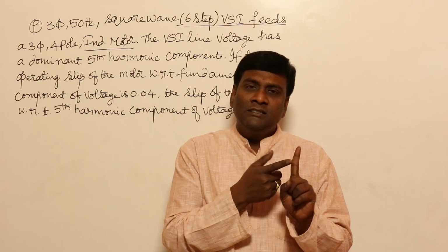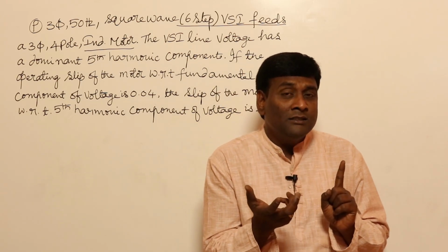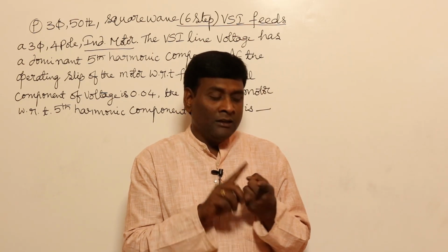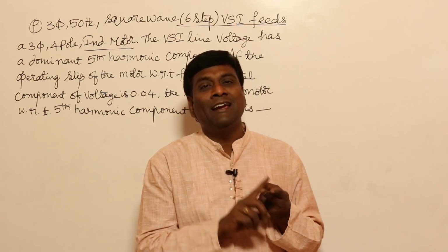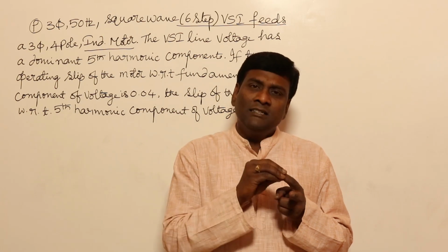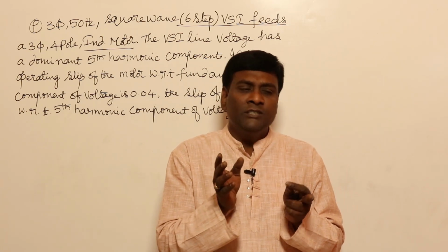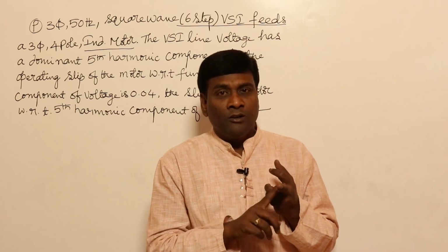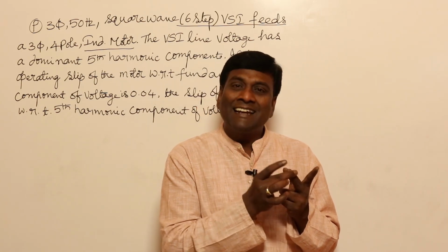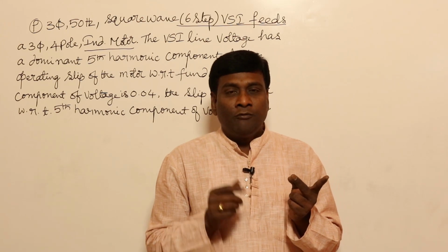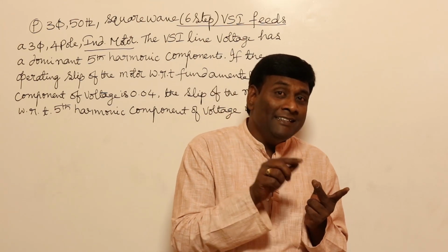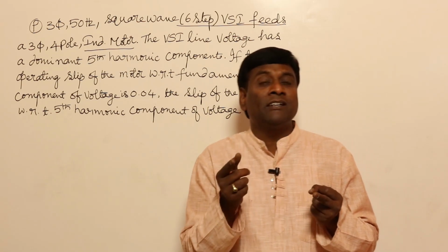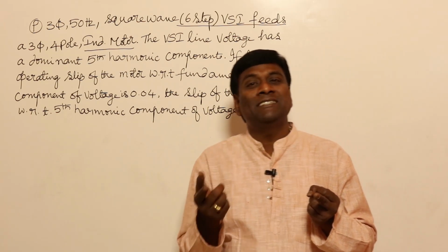So in the rotor, what will be there? In the rotor, resistance will be there, reactance will be there, because rotor analysis is nothing but induction motor analysis. Resistance will behave independent of frequency if you neglect skin effect. Forget about it for the time being. Reactance: for example, for 50 Hz the reactance offered is X. For 150 Hz the reactance offered will be 3X because the frequency is increased. For the 5th harmonic component, it will be 5X. For the 7th harmonic component, it will be 7X.